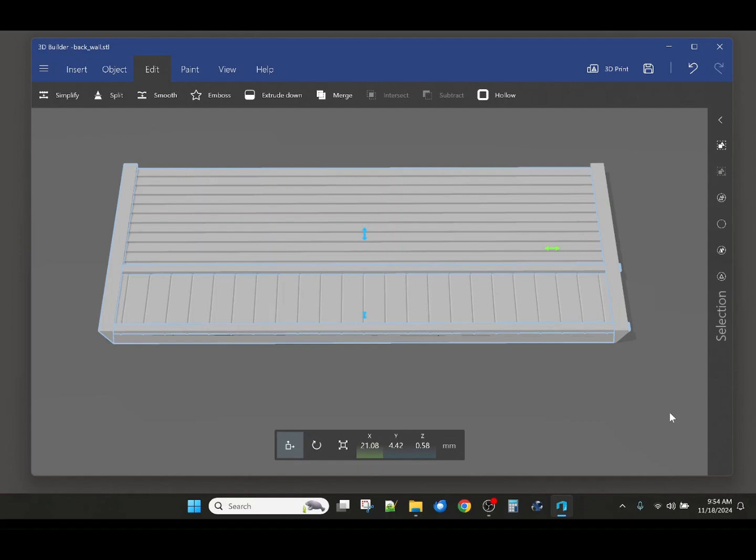The remaining work to make the front wall is to cut the door and window openings and place the door and window parts. This operation exposes a limitation of the part placement workflow, in that we're just going to eyeball the door and window positions for this model. If you were constructing a model of a particular prototype, you'd have to convert your door and window spacings to scale millimeters and use those values to do the part moves down the wall. Doable, but outside the scope of this simple project.